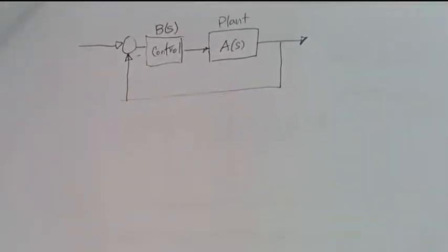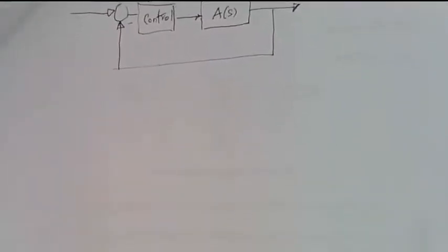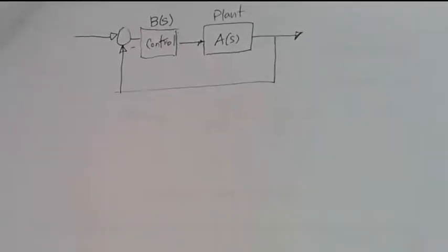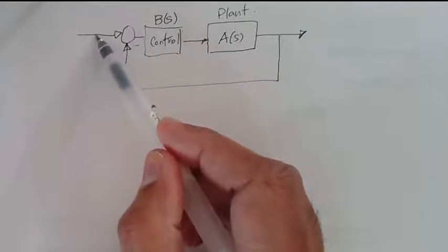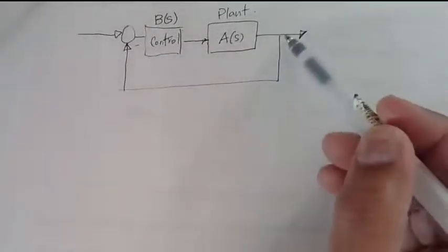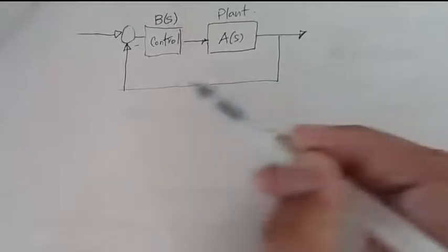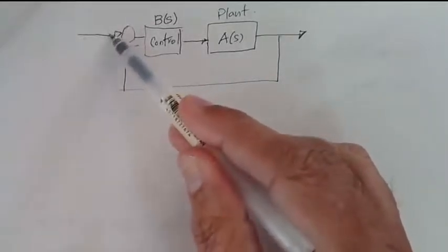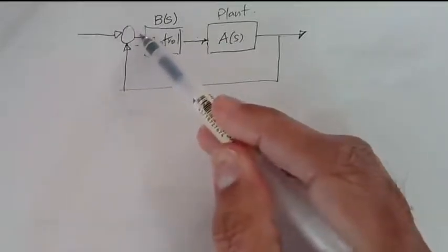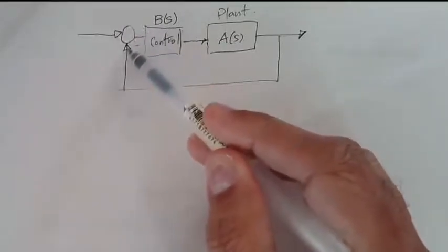Right. Another one that we will see in just a little bit is the cruise control on your car. Right, you set a particular speed that you want the car to go at, and then the system measures the speed of the car. And if the speed of the car is different from the set point, then it either increases the gas or decreases the gas.